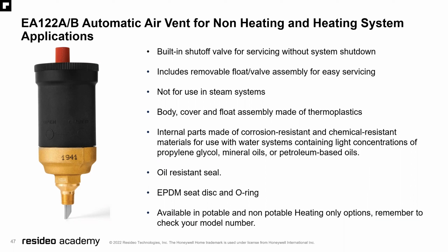Body cover and float assembly are made of thermoplastics. The internal parts are made of corrosion resistant and chemical resistant materials for use with water systems containing light concentrations of glycol, mineral oils, petroleum-based oils. Oil resistant seal, EPDM seat disc and O-ring. It's available in potable and non-potable heating only options. Remember to check your full model number.